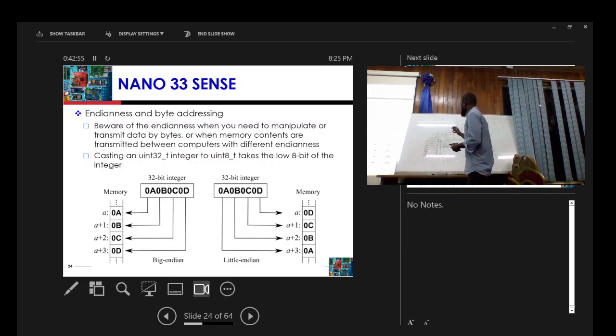If I want to address a value within this memory, I have to reference, say, this number 5, and it will pick the value from here. The width of the memory is how much it can store within just one location. Within location 0, how many bits can it store? Normally memories are 8 bits; it can store 8 bits within one location. And then the depth of the memory is how many 8-bit locations there are within the memory. As easy as that. So we have the width and then the depth.